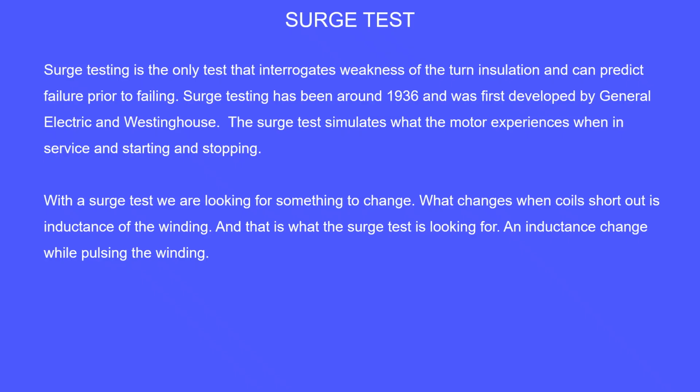With the surge test, we are looking for something to change. What changes when coils short out is inductance of the winding. And that is what the surge test is looking for. An inductance change while pulsing the winding.